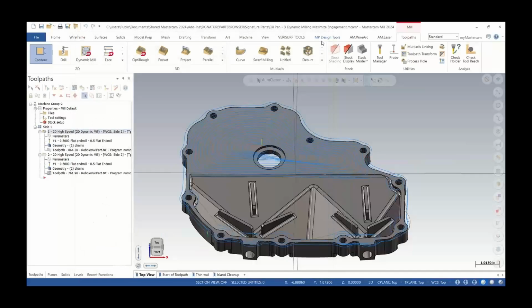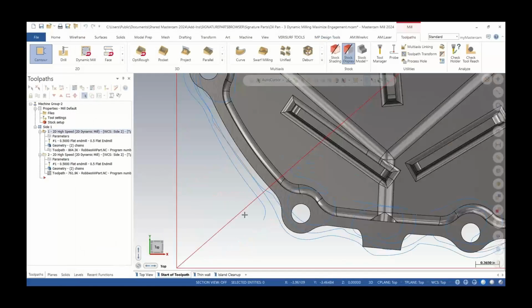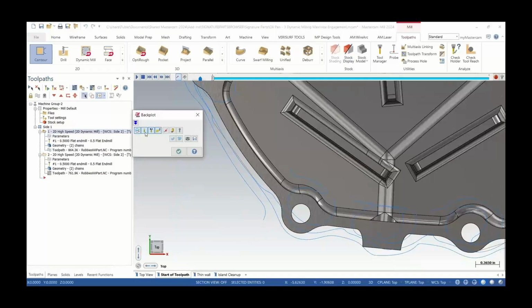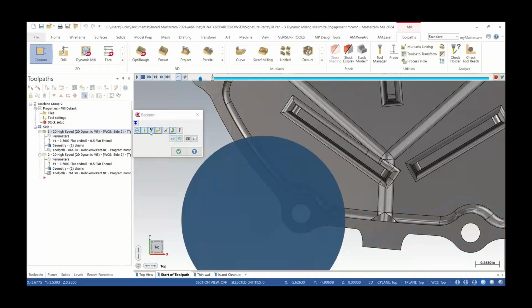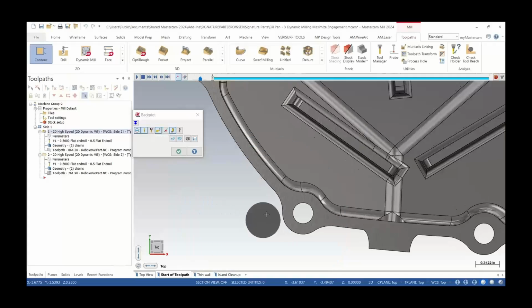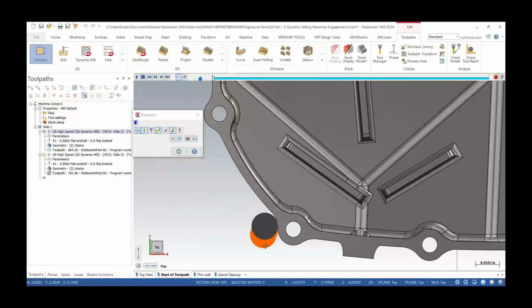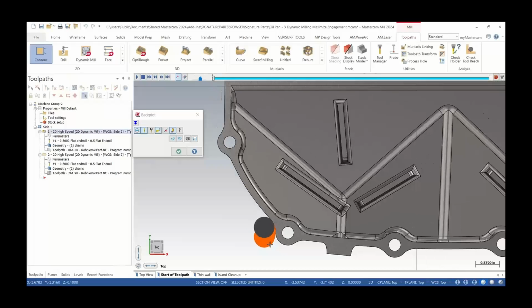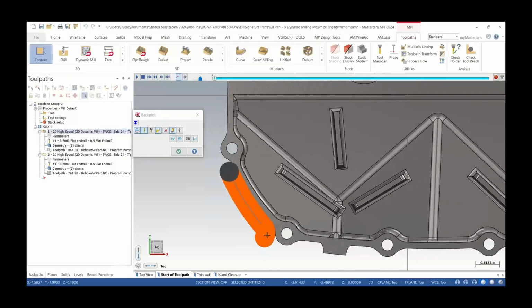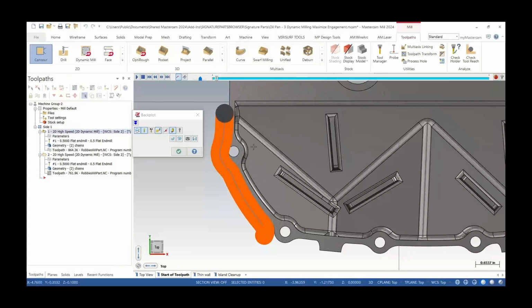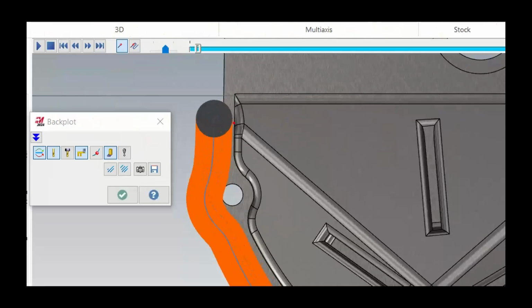And if I display, let's say, the start of this toolpath here with maximize engagement off, I'm going to turn on my simple verify and just remove the holder for better visualization. And using dynamic, we can see it often takes a while to gradually reach the step over we have desired.